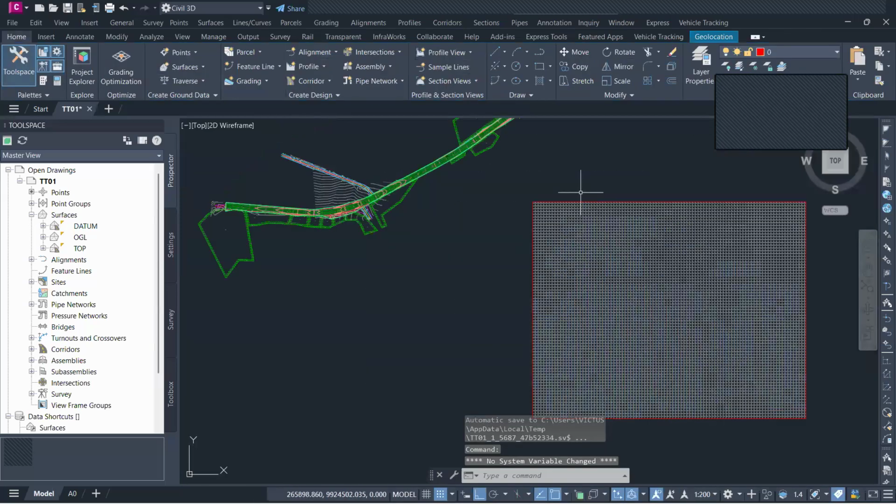Let's say we have imported those points and you will create a new surface. That means you're going to have two surfaces. So every day you're going to check, and then once you check, you bring it here and create a surface. You will call it day 1, day 2, day 3, day 4, day 5. Now, you as the design engineer, as the CAD technician, as the surveyor, or as the cost engineer, you are monitoring the earthworks and quantities. The software here sometimes may have some differences due to the triangulation.